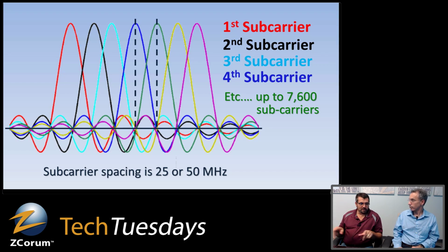They also do time division interleaving and frequency division interleaving, where they send different bits of the same code word, depending on how your settings are set up, in case you get interference. If you've got ingress bursts or whatever, they send pieces of it a little bit over time and across different frequencies, so that it doesn't crash. In a SC-QAM, you get a time slice and you're on this frequency, right?